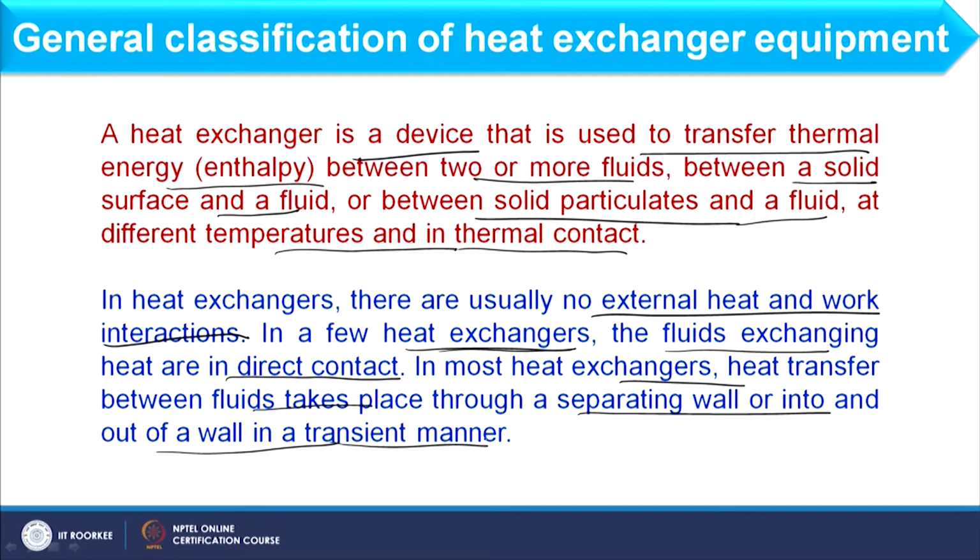Sometimes it is with direct contact, meaning two fluids are in direct contact, as I have already told you that if sand is heated up, it can transfer heat to the air near to it. There we are not providing any media or any separation between them, so they are in direct contact. In a similar line, if I put a separating wall between two fluids, it is called indirect heat transfer. So, heat exchangers work on both principles, direct contact as well as indirect contact.